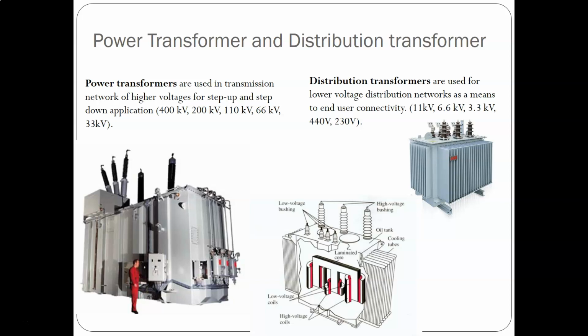So for how it's designed, it's of course important how they are going to use it. Power transformers used in the transmission network are not directly connected to the consumers, so load fluctuation is very low compared to a distribution transformer. That means these are loaded fully during 24 hours a day. So copper losses and iron losses stay very constant throughout the day.